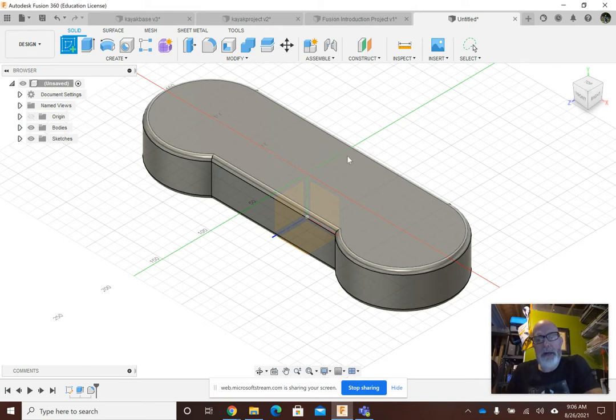One thing to keep in mind, I don't want to click where the plane overlaps with the surface I want to click on, because if I click there, it will select the plane. It's going to default to the plane in the areas where the plane and the surface you want to sketch on overlap. So instead of clicking here, I'm going to go up out of the way of the plane, away from it, and click on the surface up here.